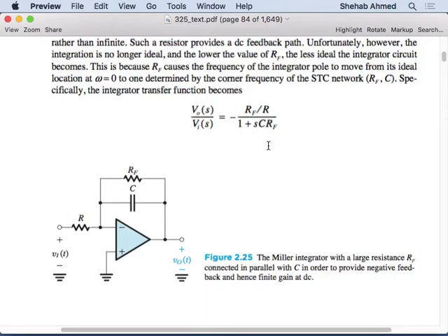Right? So if you have a ramp, it will slow down the ramp because a ramp has certain frequency content. Assuming this ramp is periodic, for example, it's a function that is non-sinusoidal. I can analyze it using Fourier series, chop it up into a number of sine waves. If I add these sine waves up, I can create this ramp.